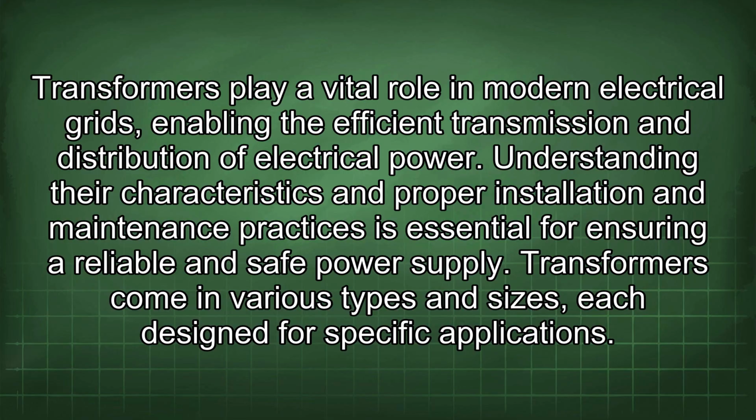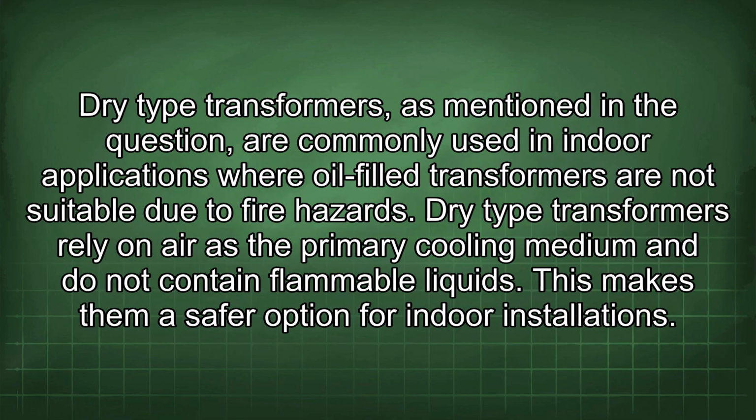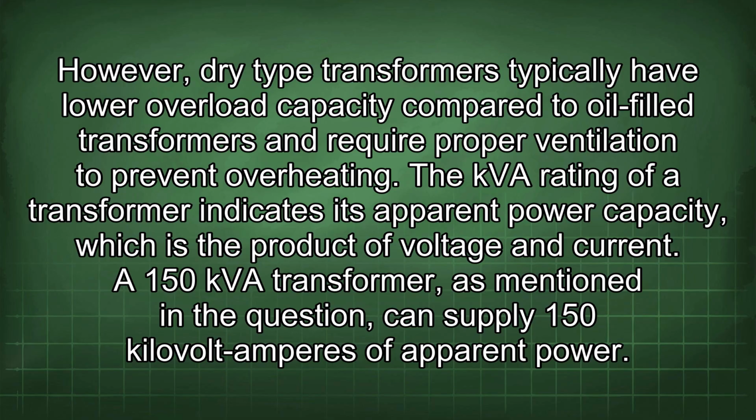Transformers come in various types and sizes, each designed for specific applications. Dry-type transformers, as mentioned in the question, are commonly used in indoor applications where oil-filled transformers are not suitable due to fire hazards. Dry-type transformers rely on air as the primary cooling medium and do not contain flammable liquids. This makes them a safer option for indoor installations. However, dry-type transformers typically have lower overload capacity compared to oil-filled transformers and require proper ventilation to prevent overheating.